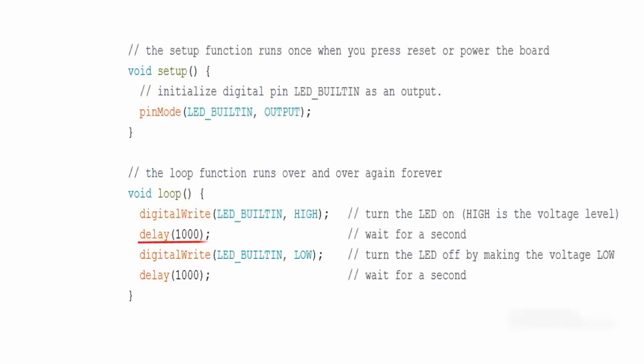The delay function call causes the program's execution to pause for 1000 milliseconds or 1 second. Because the LED is turned on, this has the effect of letting us observe the LED with illumination. If the call to the delay function was left out of the program, then the LED would be turned on for such a short period of time that our eye would not even be able to tell that it was ever on. Therefore, the delay function call serves as an extension of the output step of our 5 program steps by letting us observe the current state of the LED.